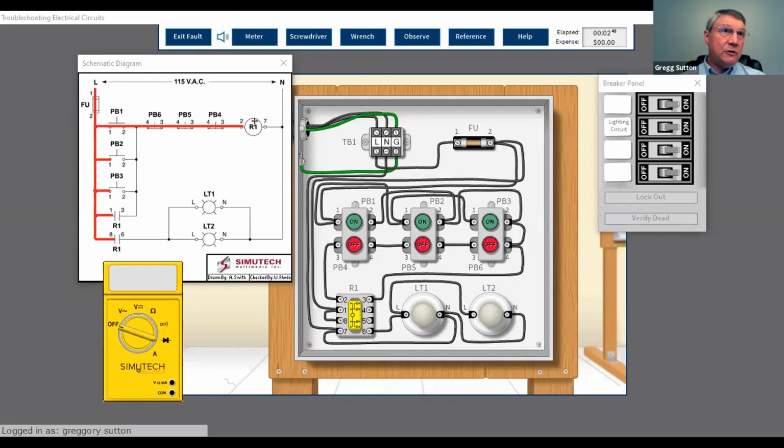Well, the first thing that happens when we energize this coil is this set of contacts changes state and the lights come on. That's what should happen. We've got our finger on the button now, right? And the lights are on. In addition to that, this set of contacts is going to close as well. And what we're going to see is a second path to that coil. And what that allows us to do is take our finger off of that push button there, like this. It opens that up, but we still have power to the coil.